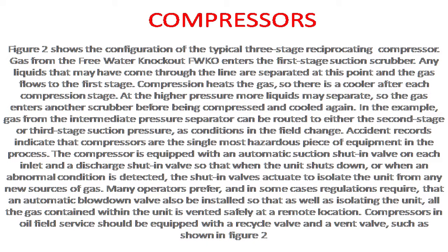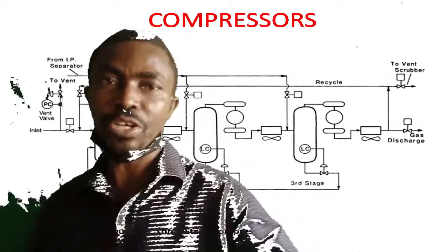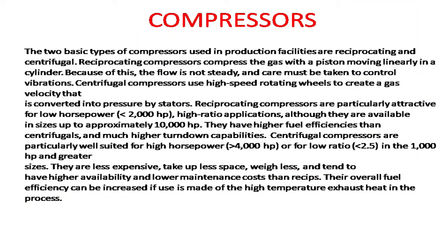In this manner, the liquid dump valve is constantly adjusting its opening to ensure that the rate of liquid flowing into the vessel is matched by the rate out of the vessel. So that's how you achieve level control. Let's go to the next slide.